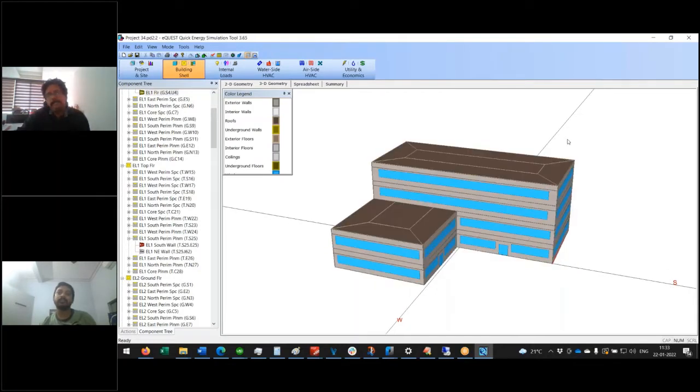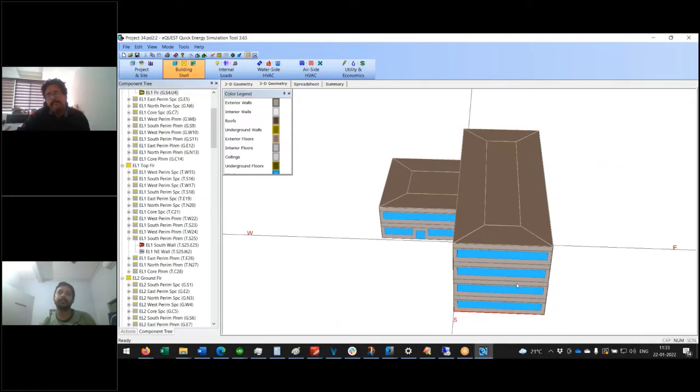So in the early morning, this entire block is shading this portion on the left side. The right block is shading the left block, correct, in the early morning. So it's not going to consider that. It's straight away going to consider whatever projection is falling on the surface. It is going to take it as a standalone surface. So that's how eQuest works.